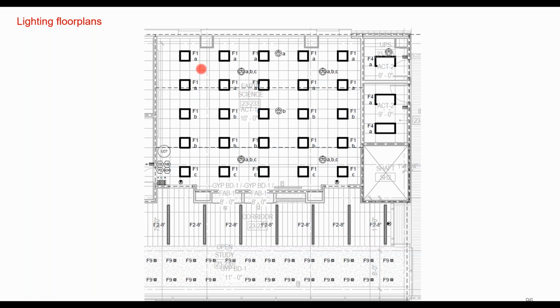You'll get a lowercase letter, and you'll have a circuit label, which is usually a small notation of a letter or number, in this case A, that shows which circuit those specific fixtures are on. You might have sensors, in this case aux sensors. You might have control switches on panels that'll tell you actually what kind of switching you have on the wall.